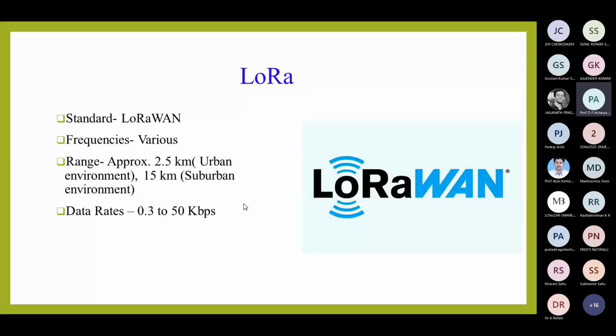All of you may know what LoRa stands for. LoRa stands for long range. It's a radio communication technique that uses spread spectrum modulation, and the range is very high. That's why it's long range. Long range means more than 10 kilometers most of the time, if you have good conditions. LoRa technology is very much used in industrial environments as a replacement to Zigbee, and LoRa uses very little power.